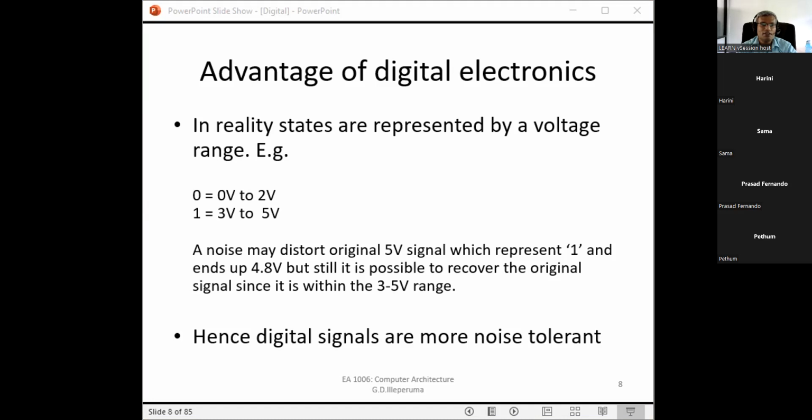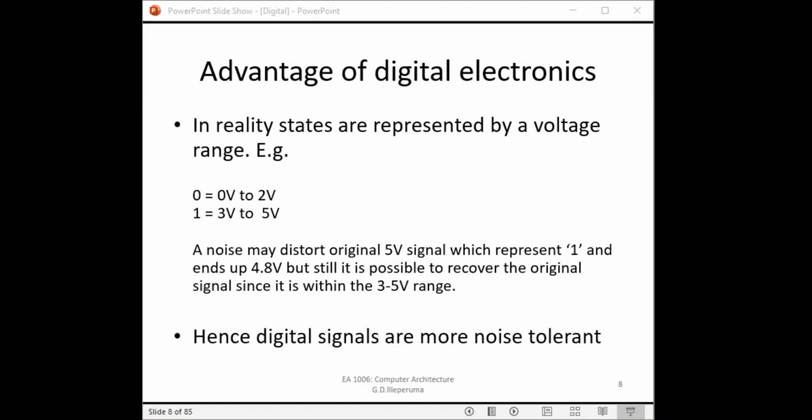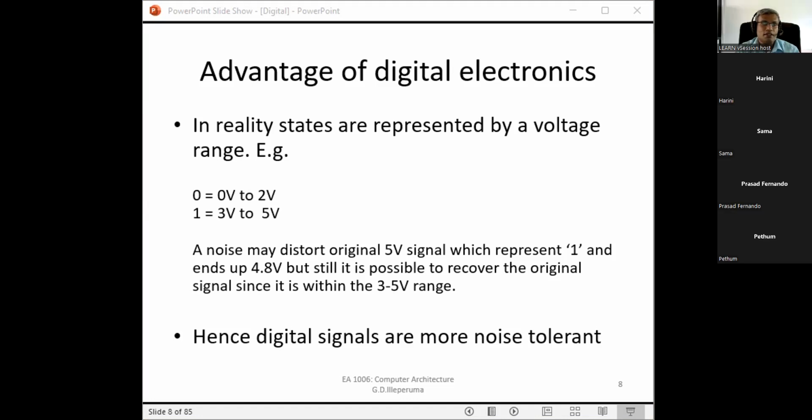The reason is when you're using a CPU, it tends to get hot, right? Higher the voltage you input into the CPU, hotter it gets, right? So we usually try to keep it cool by reducing the voltage. So the logic levels in a CPU are quite low, sometimes even around 1.7, something like that. So if you have a full supply of 1.7, you can't have a logic level of 5 volts, right? So inside the CPU, the logic levels are different, very small.